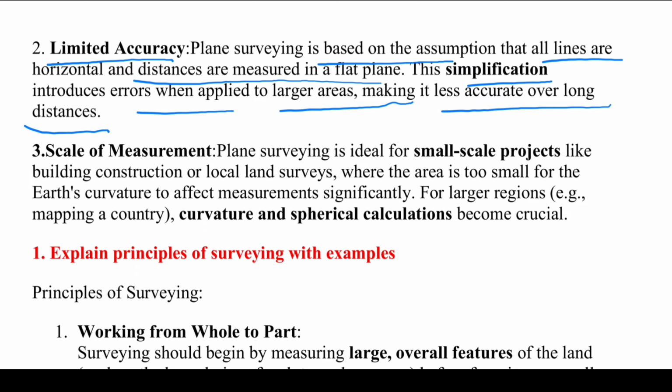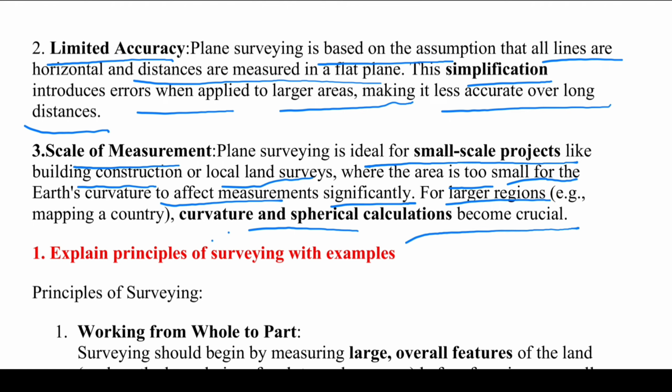And what about scale of measurements? Plane surveying is used for small-scale projects like building construction, local land surveying and just measuring land. If the area is large, the earth's curvature will significantly affect the measurements. In larger areas, the curvature of the earth and spheroidal calculations are very difficult to handle in plane surveying. That's why it is used only for small areas.